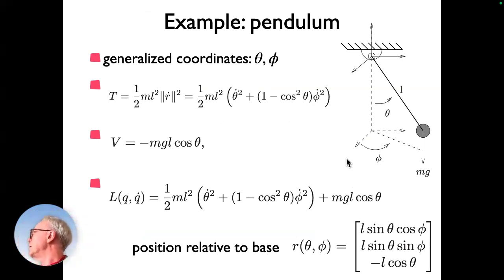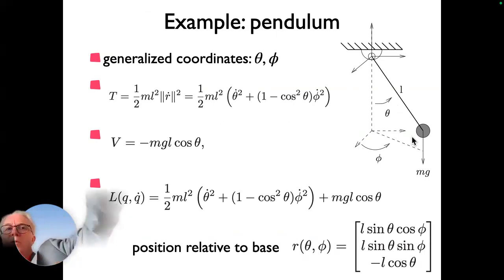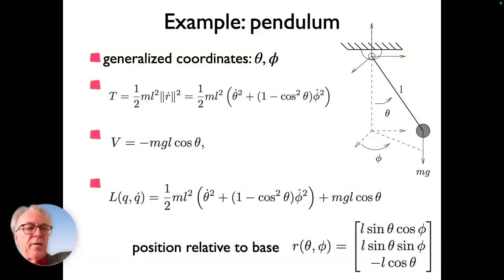So for instance, the simplest textbook example, I have a pendulum in 3D. So a rope here, a mass, which is treated as a point mass. So gravitational force on that is proportional to the mass and the gravitation constant. And it has 2 degrees of freedom, right? You can rotate in this plane, so this way or that way, or you could take an azimuth angle and then the angle within any of these planes, right? So the theta is one, and then projection onto the plane would be the other joint angle. So one is theta, the other is phi, 2 generalized coordinates.